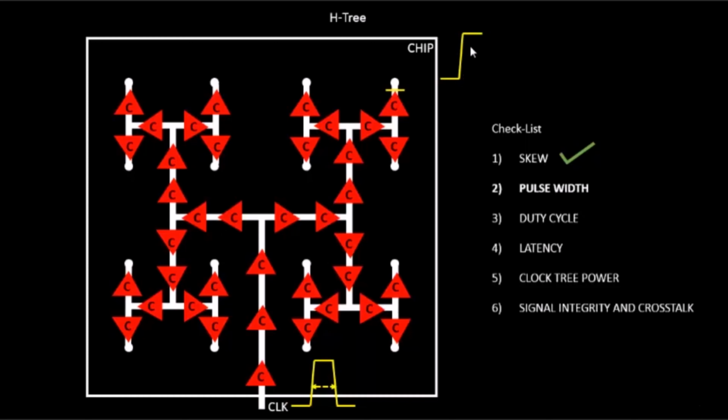The slew was at something like this. In this case, the 0 to 1 slew, or rather the rise transition time, is much better compared to what we had before, and it is also comparable with the one that we sent at the input. So we have a very good 0 to 1 rise transition time, which is good news for us. Next we will be transmitting the remaining signal, the 1 to 0 transition signal,